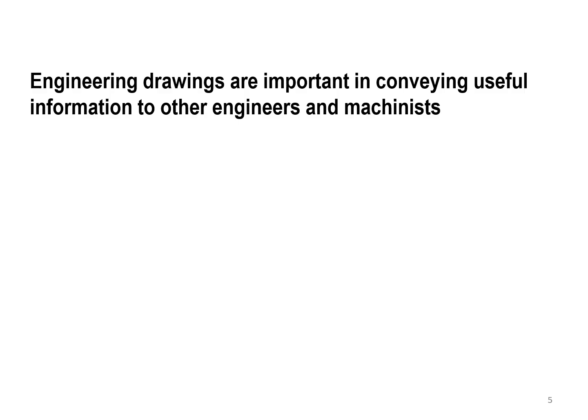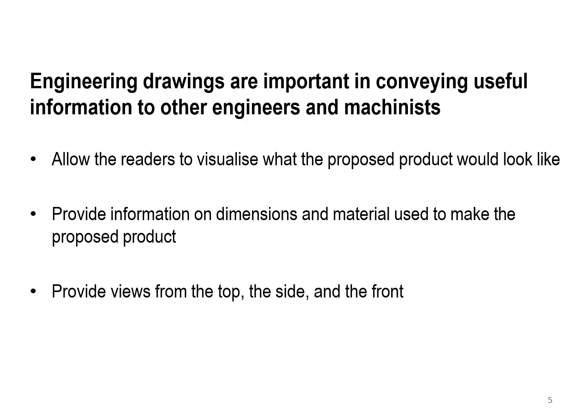So, the machinist. For example, once again, I will try to have a bar. I'm going to tell the machinist, okay, now please make me a bar that's going to have three diameter sections. The first section is going to be 20 millimeters, the other one is going to be 30, the third one is going to be 40. But I didn't give him other dimensions, for example, the width of each one, the length of each part, or the surface finishing. So that's why we need engineering drawings, so we can argue if we have different dimensions from the ones that we're looking for.